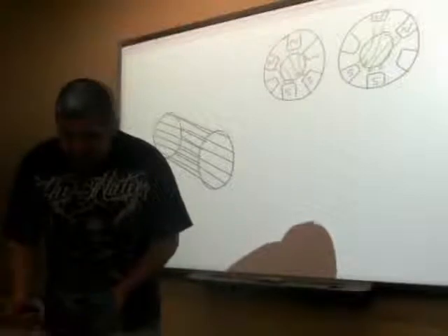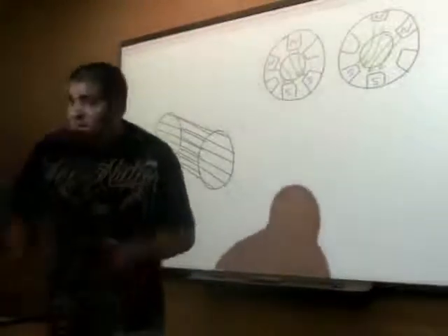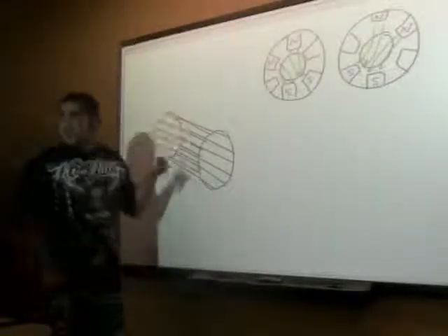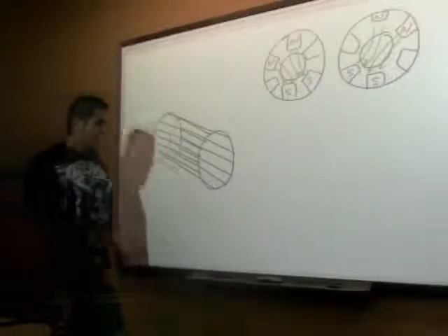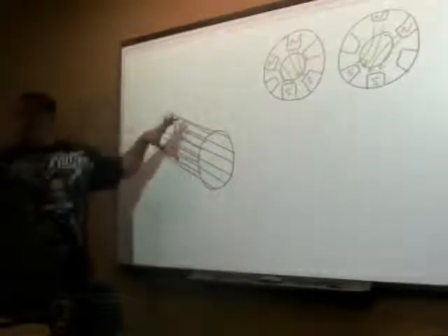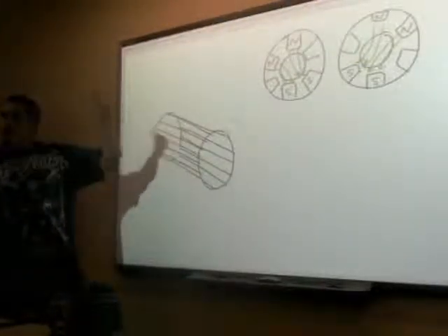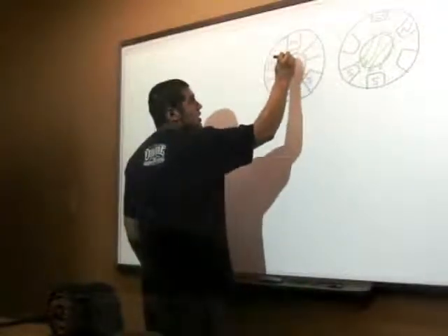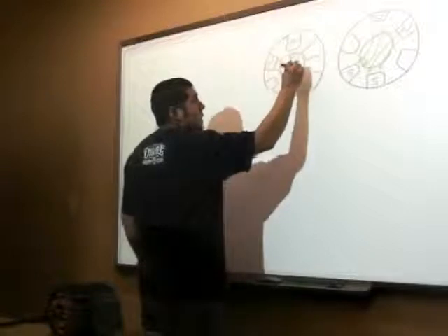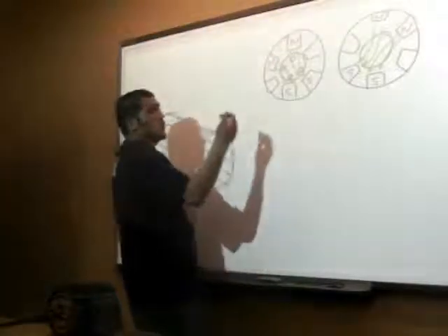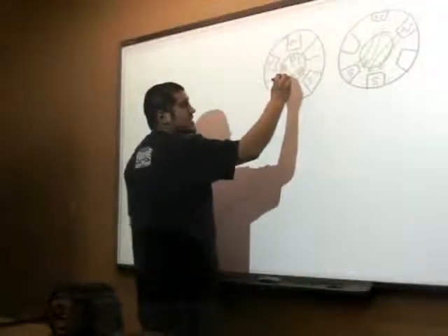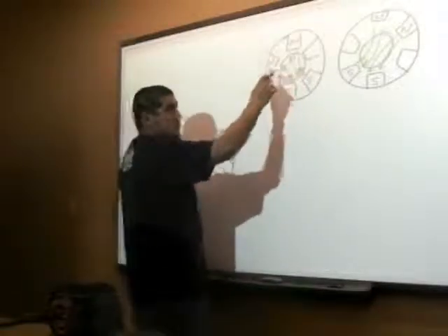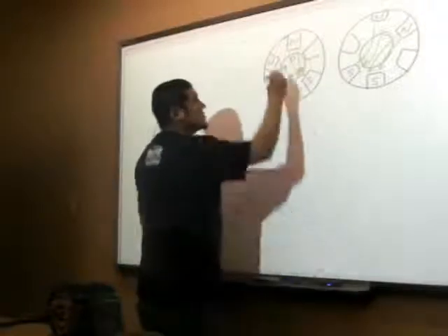This guy sitting inside of here with that rotating magnetic field cutting across it every which way, it begins to induce a current onto here. And what happens is it induces an opposing current. So we have a bar and a bar and a bar and a bar. What we induce here is it's opposing. So these are north poles and these are south poles.